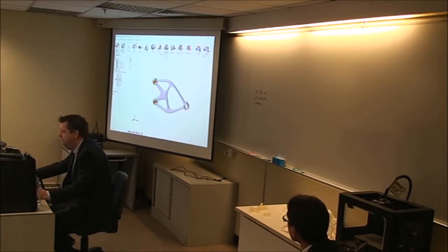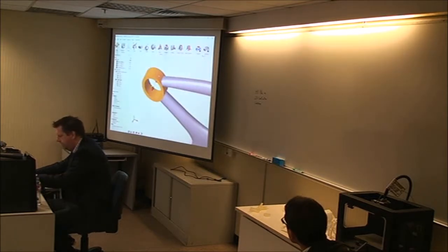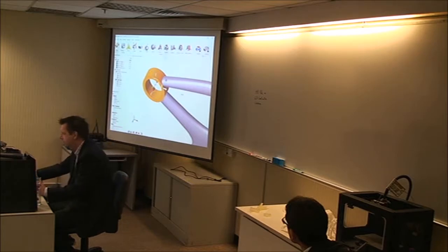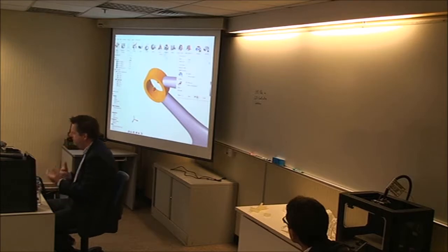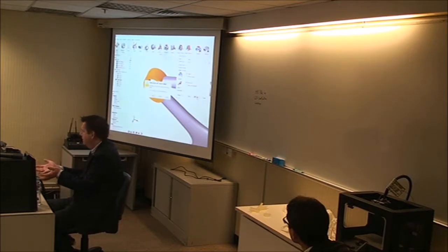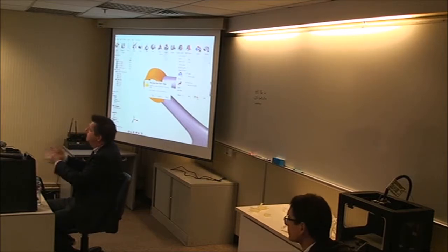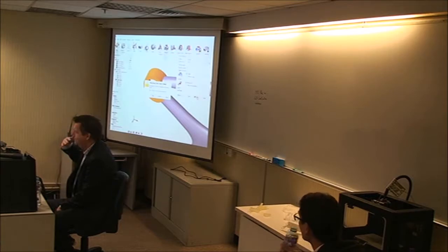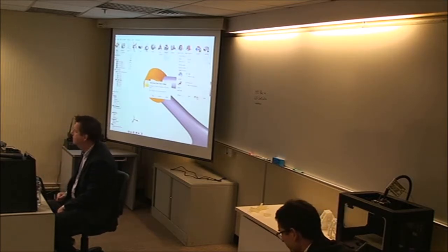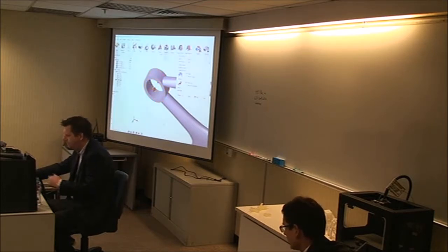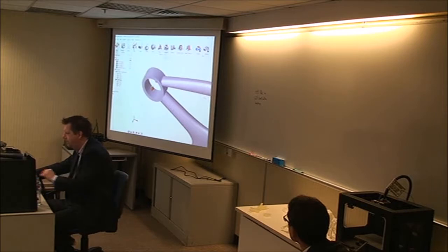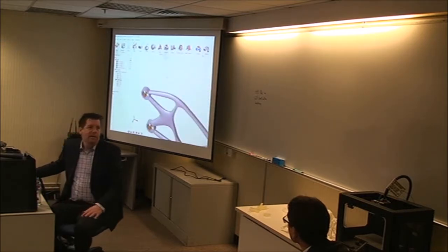So to answer this question, what sort of things can go wrong? For example, if I move that to there, so it's just overlapping a little bit, I'll make it overlap a bit more. When I try and run that, because that's bad geometry, I should get a warning that the two parts overlap, and it tells you what the parts are. So it says intersecting parts found, it tells you to go and fix them. It's one of the philosophies behind Inspire, we try and catch all that stuff and give good information. And if you've just done something stupid like that, I can Control Z, I can undo everything. It should be fixed. So that was my quick example.